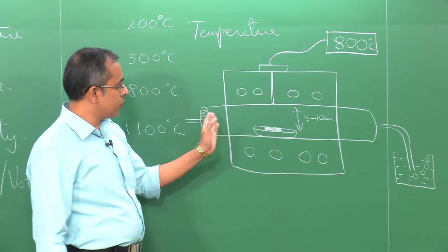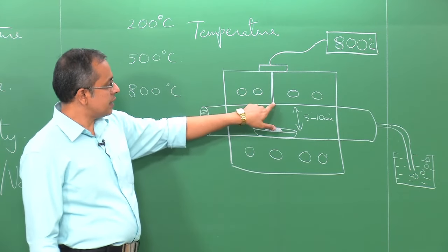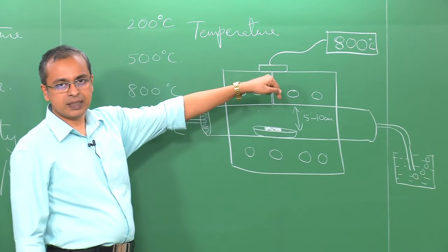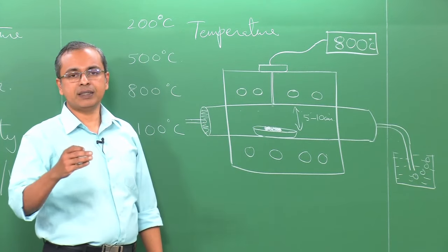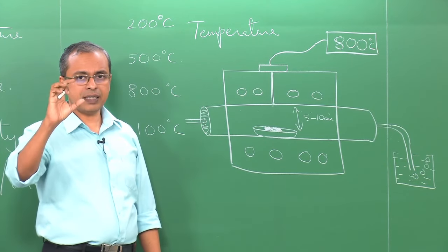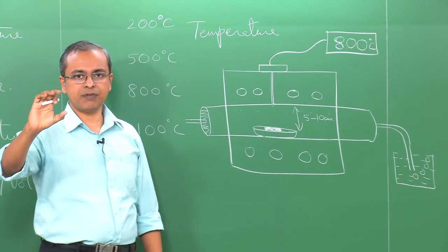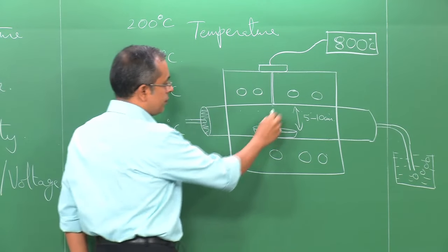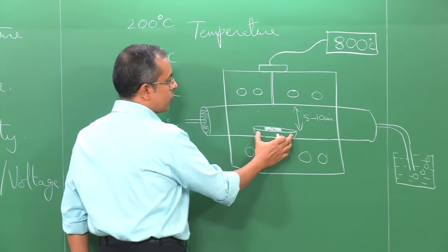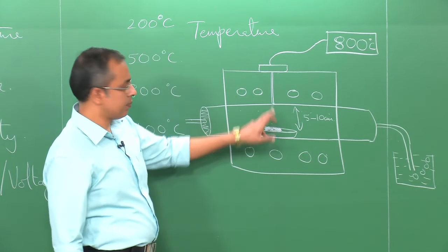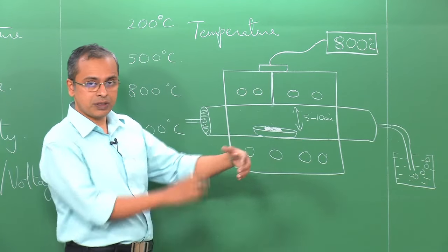And in this region you could have gas flowing, you could have a lot of different things happening, and therefore, even though your thermocouple is registering 800 degrees C, your actual sample may be sitting at 750, 760 degrees C. The cooling could easily cause that 50 degrees difference. Even vertically there can be a difference in temperature, horizontally also. Your boat may also not be positioned exactly below the thermocouple, it may be a couple of centimeters ahead or behind, because it is a long tube.